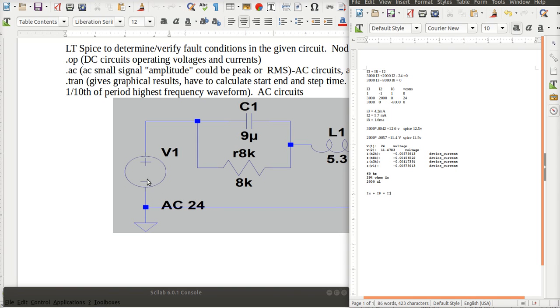Okay. When I do the circuit analysis, I'm going to do around the loop again, just like I did last time. So when you're doing AC analysis, even though AC is constantly varying, you take a snapshot of it and write the equations as if it's DC. So there is a moment in time when this is positive with respect to this one, it's negative, and it's worth 24 volts. So at that moment, I'm going to write the equation because it all has to work out.